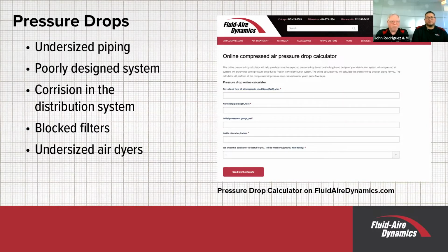One of the things you have to watch for excessive pressure drop in would be filters. We just talked about filters. But what happens when they get dirty? You should change them once a year. But if in fact you have a very dirty environment, foundry or something like that, you may find out that the filter gets blocked a lot sooner than 1 year. The pressure drop across them can be enormous. You could have a filter that's designed for a 1 pound pressure drop, but when it's totally loaded, it could be as much as 5 or 10 pounds.